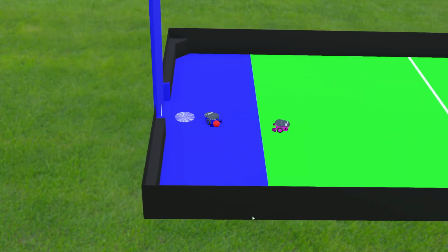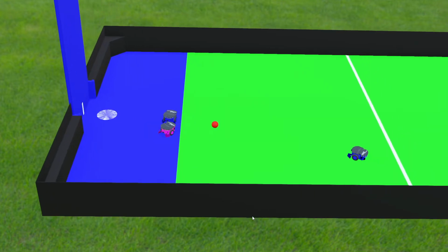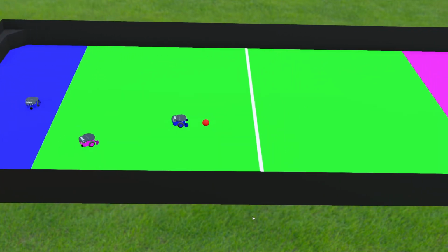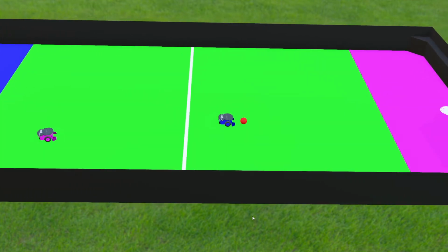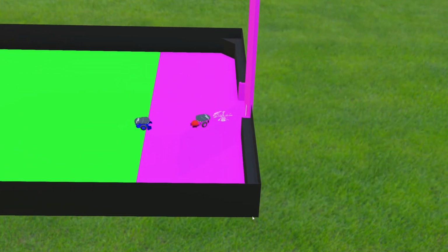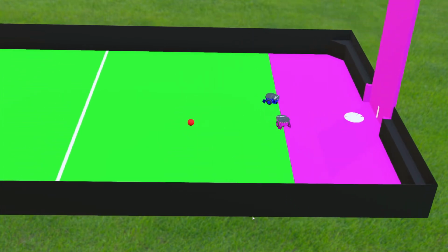I've added a thing since the report which after 50 cycles of trying to drive in that direction and it doesn't work, then it'll change the motor direction to the opposite for another 50 cycles before it'll reset out of the stuck state. Another way to reset is if all the sensors are cleared, there's nothing around.